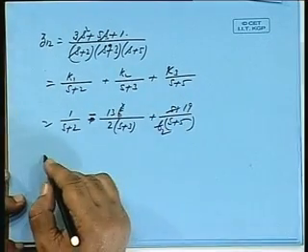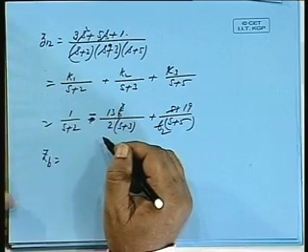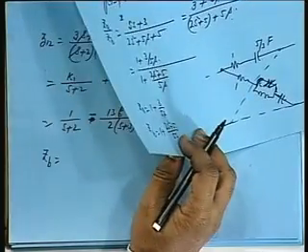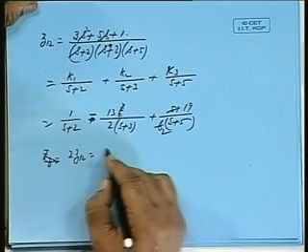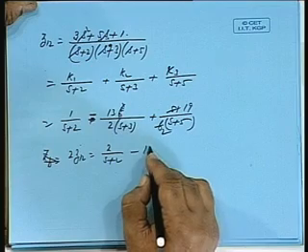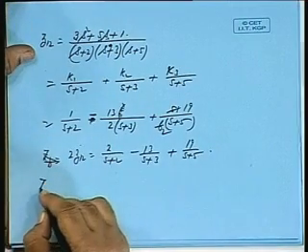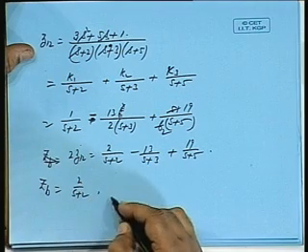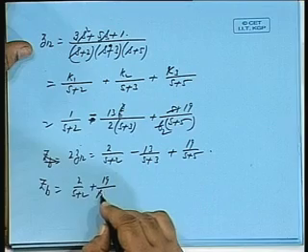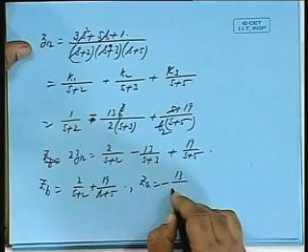Okay. So, what should be ZA? ZB minus ZA is Z12, is it? Z12 is how much? Twice Z12. So, twice Z12 we will have to calculate is 2 times this, 2 by S plus 2 minus 13 by S plus 3 plus 19 by S plus 5. So, ZA and ZB will correspond to this, 2 by S plus 2, okay, plus 19 by S plus 5, we can put it this way, and ZA is whatever is associated with the negative sign, 13 by S plus 3.